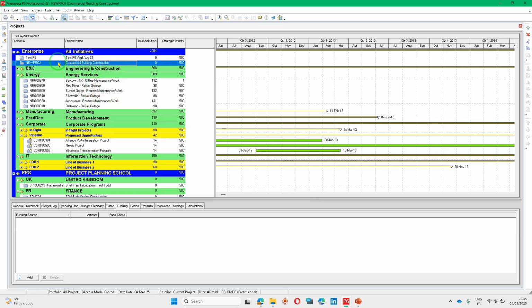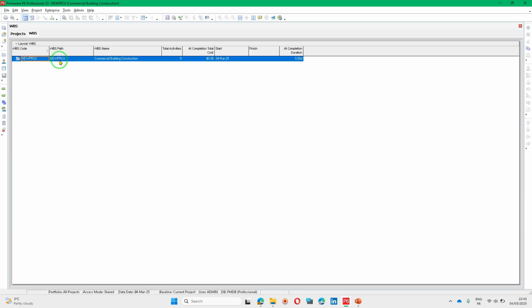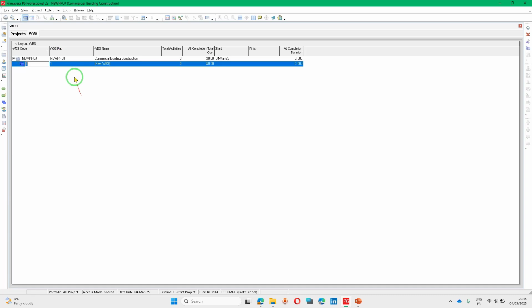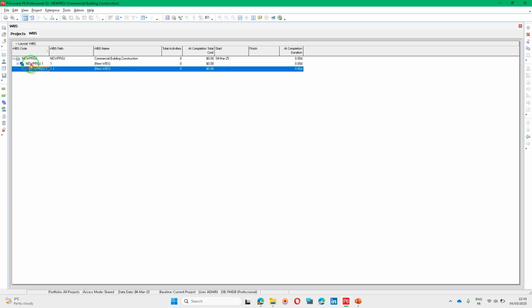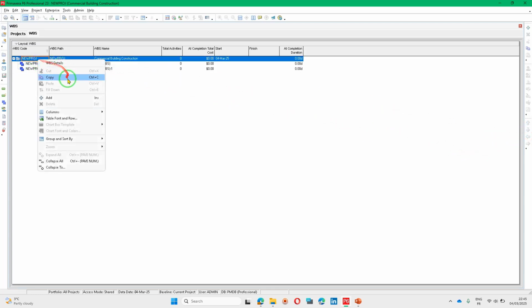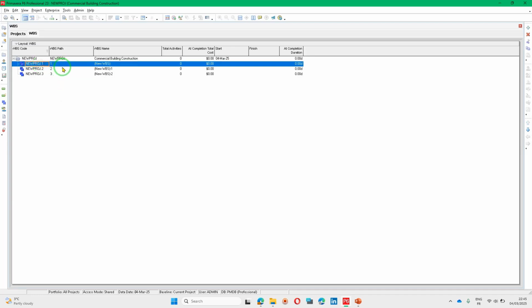Now, the next step when building the project is to see the work breakdown structure. On the left side, you have these two squares, WBS. Now, everything is empty here. In order to add a new structure, right click and click add. Now, you can again click add, and you can see this is like a structure, child and sub-level, and on the right side, you can move them one after the other and add several ones. So you have 1, 2, 3.